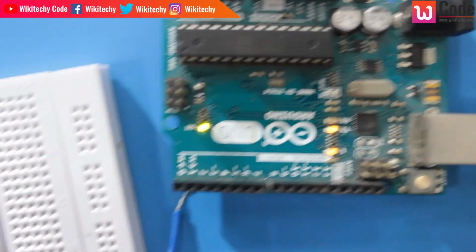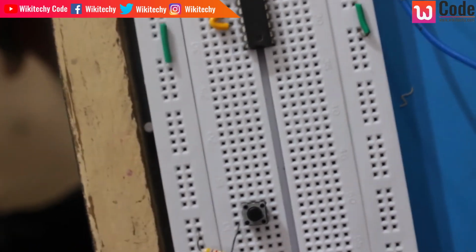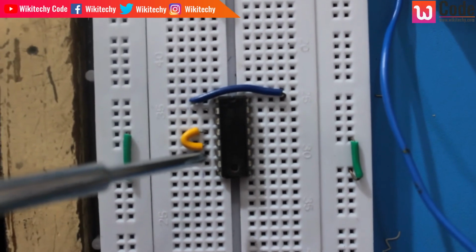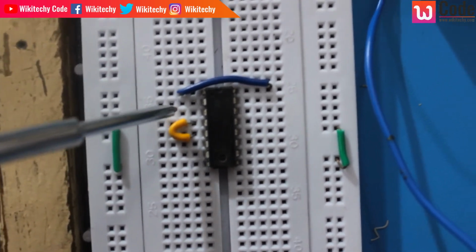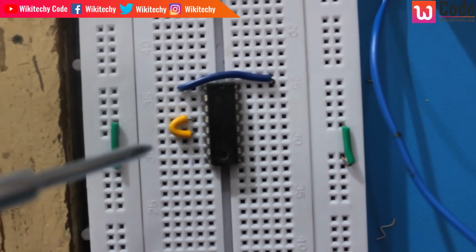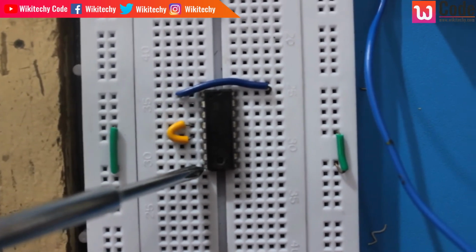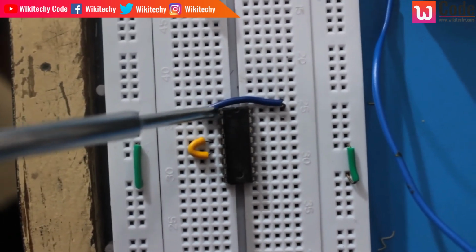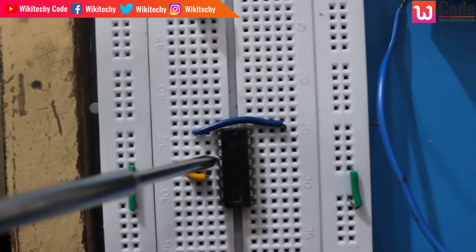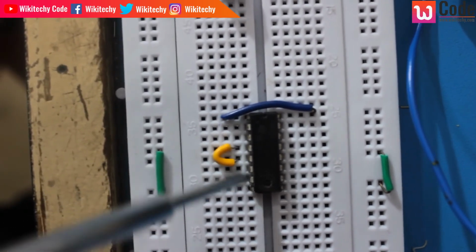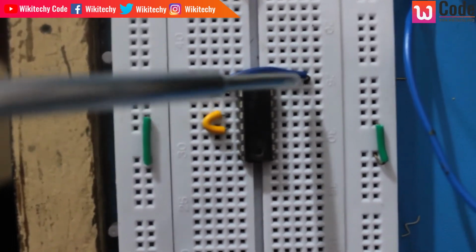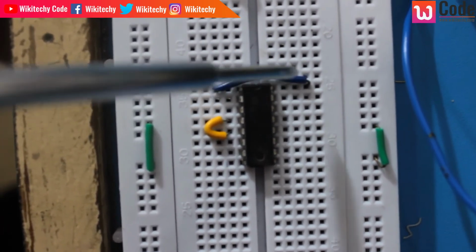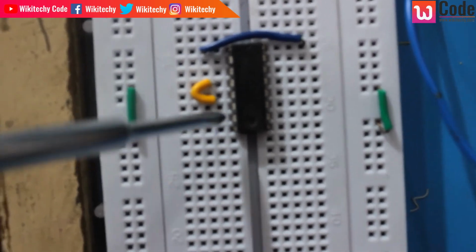Let's move on to the circuit. So for running the motor we need the IC, it's L293D. So over here you are able to see there are 2 areas of pins available, which is of almost 8 pins. Among that we got these pins available. So over here the first pin is referred to as an enable pin to enable the ports or ICs available here. On the other end over here we got the ports. This particular pin is for internal voltage. Over here the last pin is to supply for the motor.